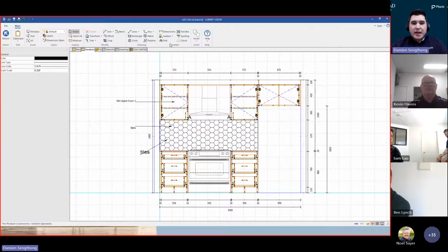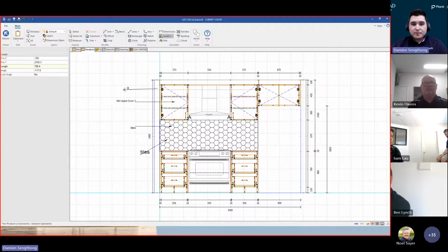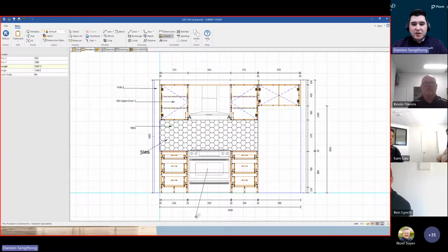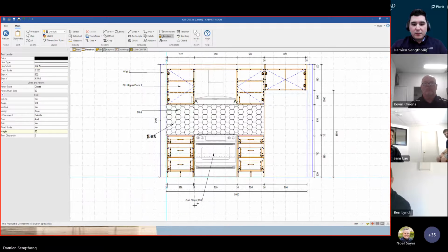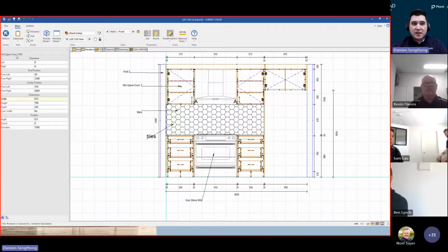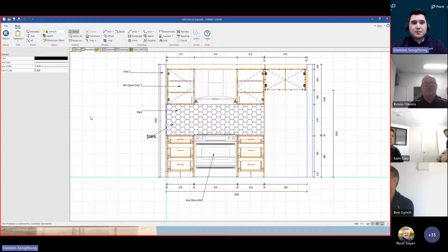It not only just works for cabinets, you can use it on walls as well. You got wall 2 and any appliance that you may have on your drawing. Now it will follow the name of the assembly, as you can see here. So if you do have specific naming conventions, it will display that on the text. Which moves on to text.